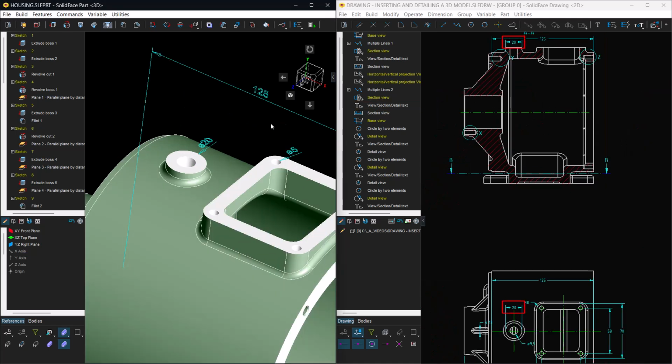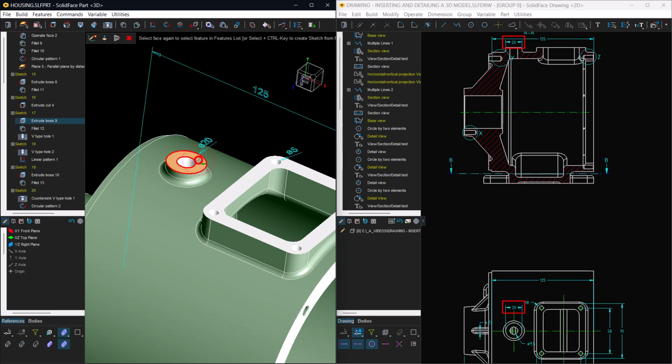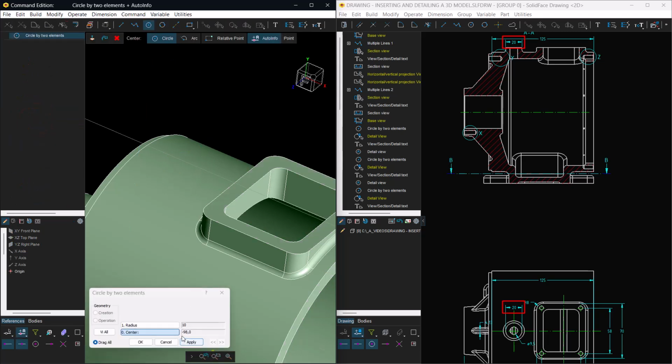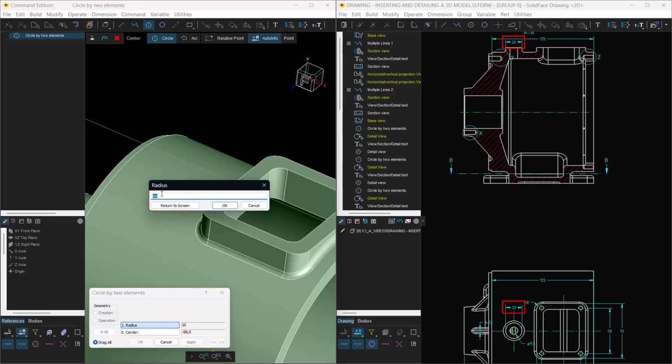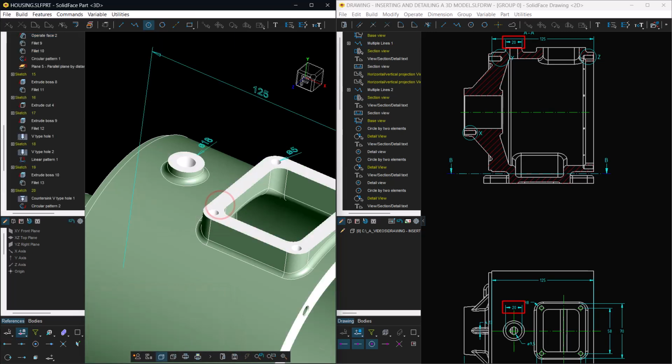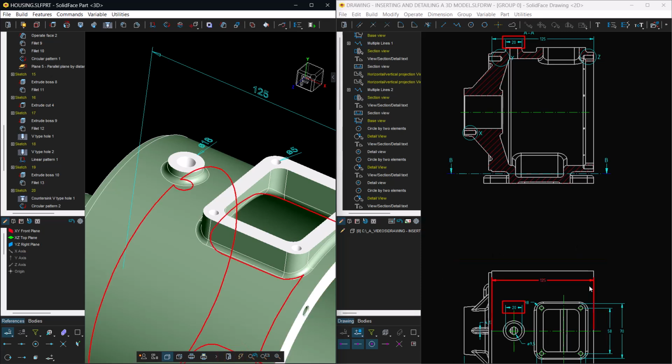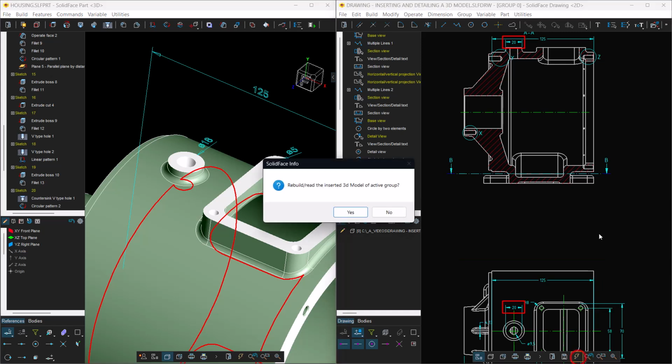In the 3D model, edit the diameter of the boss from 20 to 18, that is, a radius of 9. Click on the feature to check which sketch contains the base circle for creating this feature, editing the circle to radius 9. The diameter of the boss feature has been modified. Save the 3D model. Reprocess the drawing.